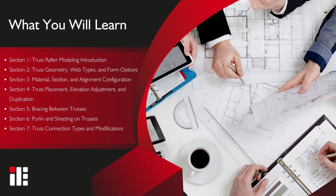Trusses are placed, elevated, and duplicated across spans with precise control. Bracing is added between trusses, and purlins and sheeting are applied along the top chords. The video concludes with an internal node detailing the end plate connections for structural support.